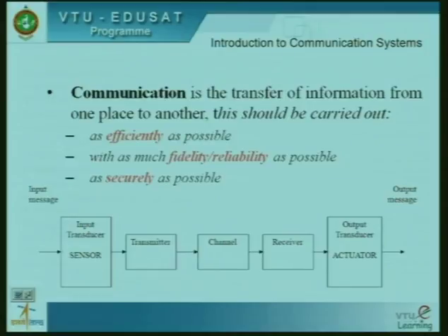If a signal has to be launched onto a channel, we need a transducer there, which converts an electrical signal back to a physical quantity. In our case, the channel accepts electromagnetic waves. So, to convert an electrical signal to an electromagnetic wave, we use an antenna. An antenna is basically a short conductor which takes in alternating current and converts it to an electromagnetic wave, and that is what forms the transmitter section, or what we call the source.